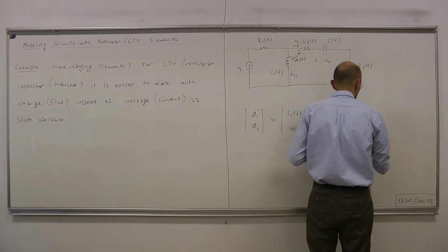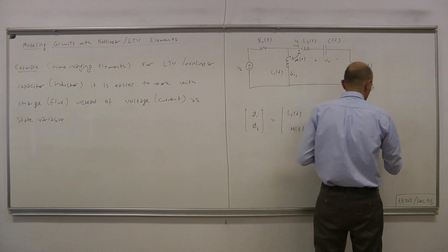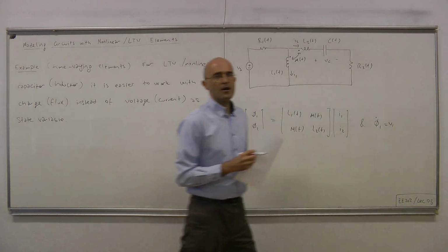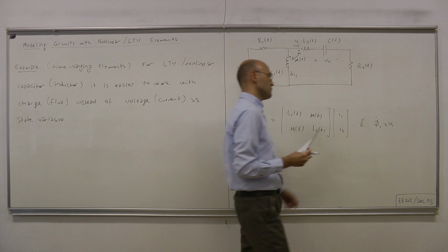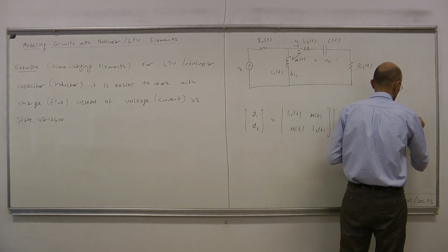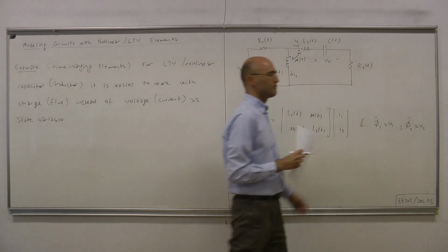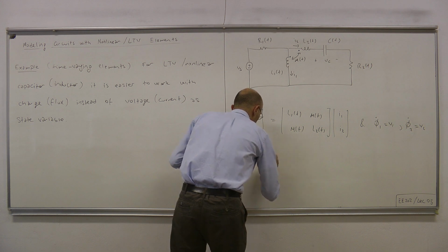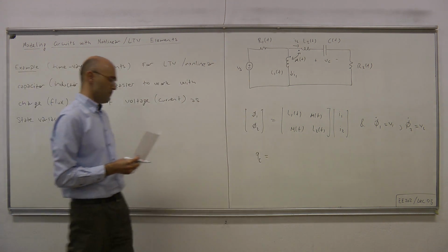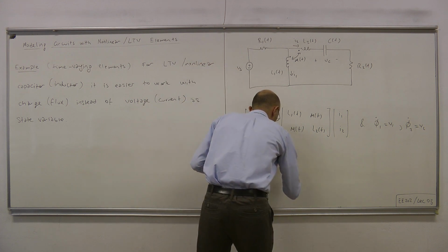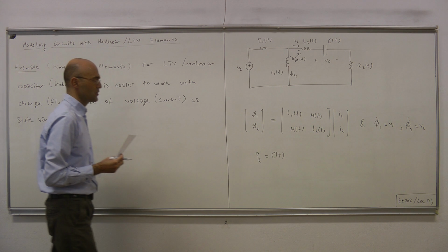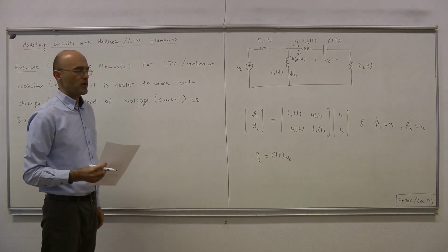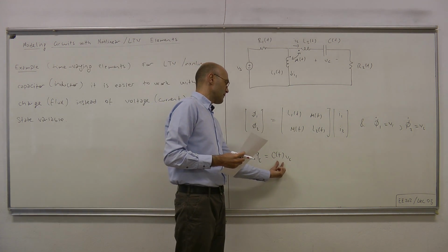And furthermore, we have Faraday's law, rate of change of flux equals voltage. Okay, phi dot equals v. As for the capacitor, the charge, let's call it q_C, is proportional, at any given time, to the voltage, but the proportionality is not described through a constant, but a time-varying scalar.